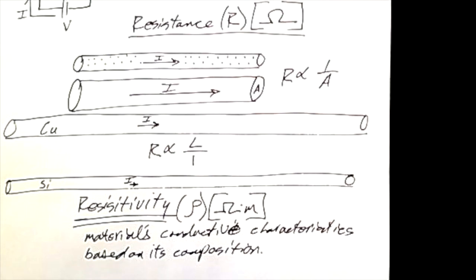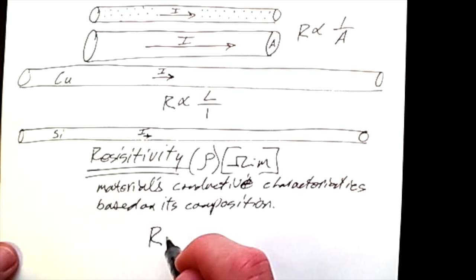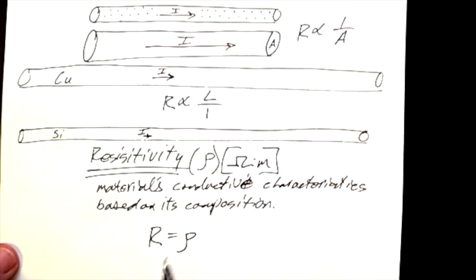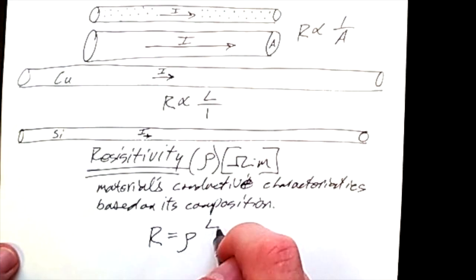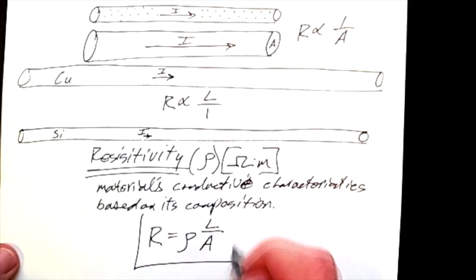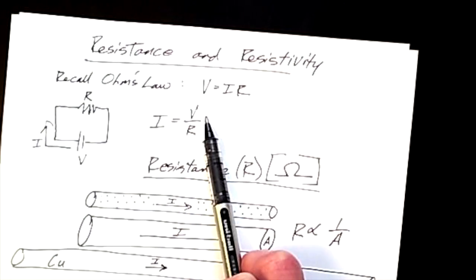Right? And so putting these things together, Ohm was able to describe resistance as being a proportionality constant based on the material that it's made out of, now known as resistivity, directly proportional to its length and inversely proportional to its area. This formula describes how we would determine the overall resistance without actually measuring the current based on a potential applied to the system.